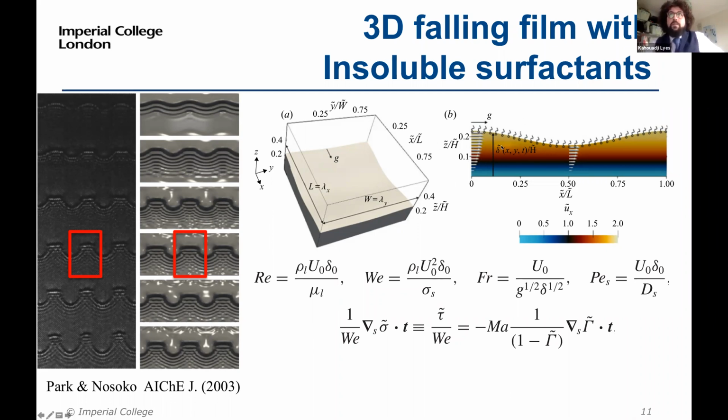And this, on the right, is the initialization of the velocity. We initially perturb the interface. We could start with a flat one, but we initially perturb the interface with a sinusoidal function just to make the simulation quick.